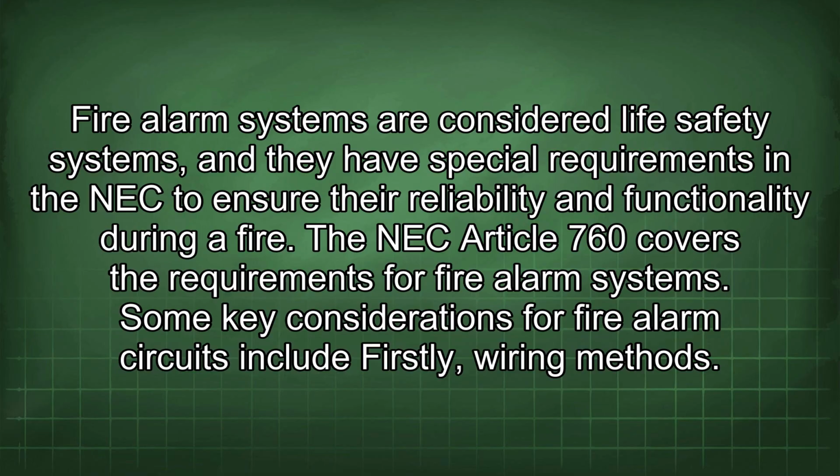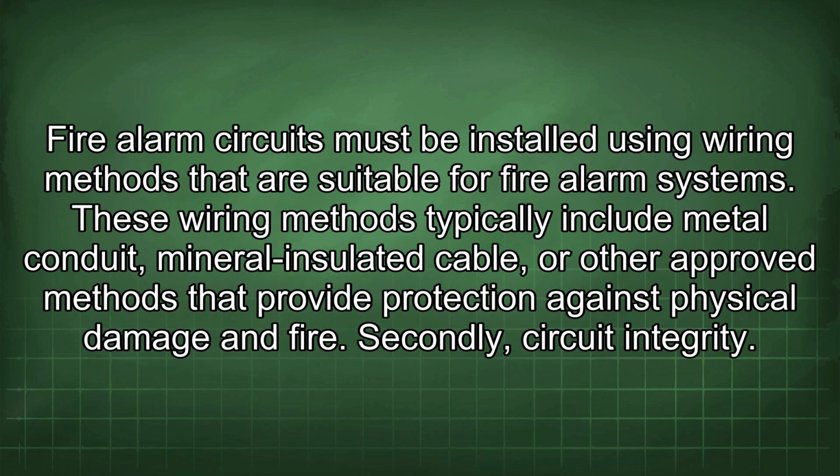Some key considerations for fire alarm circuits include, firstly, wiring methods. Fire alarm circuits must be installed using wiring methods that are suitable for fire alarm systems. These wiring methods typically include metal conduit, mineral insulated cable, or other approved methods that provide protection against physical damage in fire.